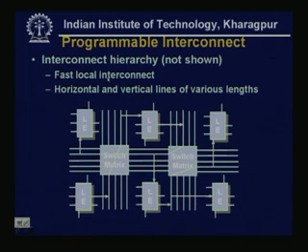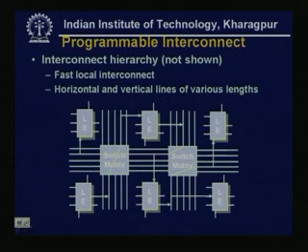Interconnect means, we know, that this is nothing but switching. Suppose I have a fixed wiring, a 2D structure of wires, with some rows and some columns of wires. Which wire is to be connected to which, meaning which row is connected to which column, is nothing but the switch. That is why the programmable interconnection can be treated as a switch box.